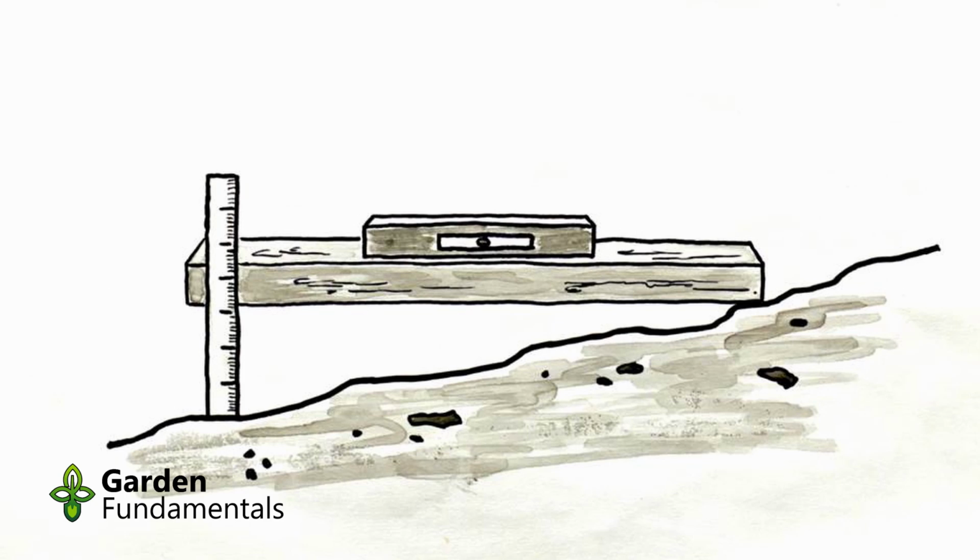So let's say the measured distance is 3 inches and my board is 8 feet long. I now know that the slope is 3 inches every 8 feet. Then I take this board and move it along 8 feet. So I put the one end where the ruler is and move the ruler down to the other end of the board. And I can work my way along a lawn and measure the slope every 8 feet. And this is accurate enough for the kind of work we're going to do.